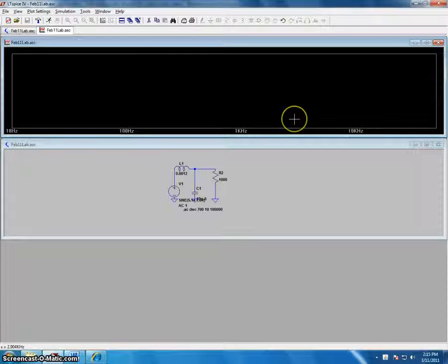I'm going to explain how to work with LTspice properly. We have 9 tasks to perform, and first of all, how to use voltage and current probes, to measure the voltage across an element and a current through an element.